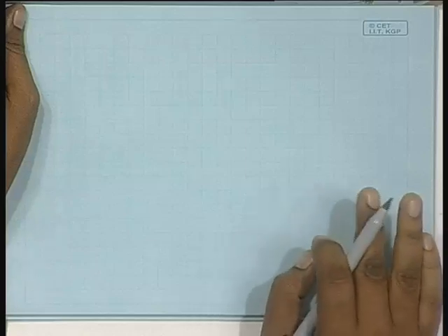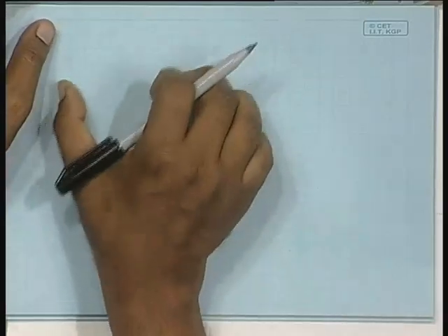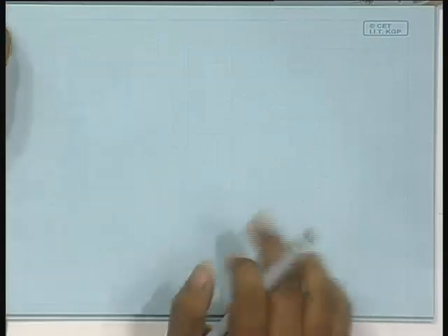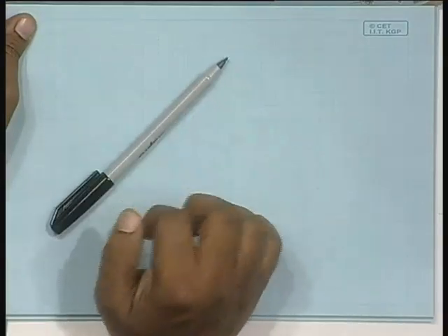Anyway, another result. Now I come back to my context. Another result, we will just present the result and store that result somewhere for our future consumption. Suppose I do not do zero padding in both; whichever is the shorter one, I add those extra zeros only to that sequence, so that both the lengths are the same, and then do circular convolution. Obviously, I will not get the correct linear convolution result, but it is still something better than not doing any zero padding at all, isn't it?